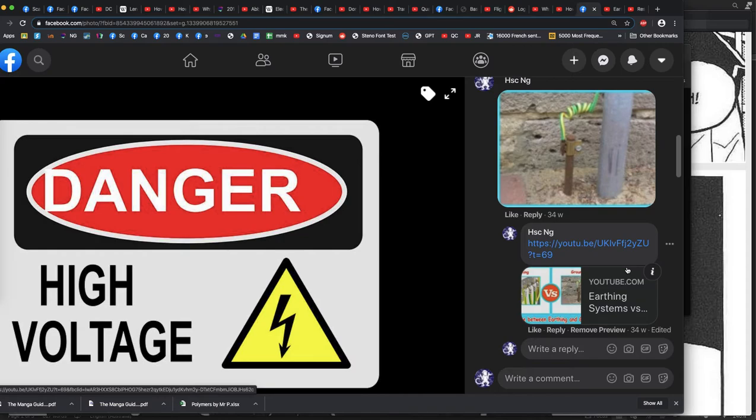We can be more conductive if you're sweaty or wet, if you've just had a shower, if it's raining, all those sorts of things make you more conductive. But generally speaking, given the opportunity, if you touch an object that has a frayed wire, the electricity would rather go through the earth wire than through you. I guess that's sufficient for me to say here.